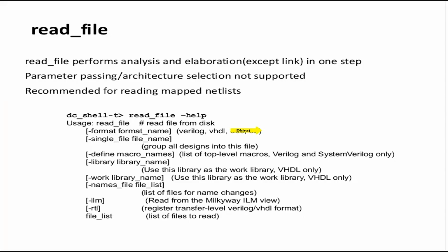However, you can use this to read the RTL also, if your RTL is simple enough. If your design does not have a parameterized design, you can go and read about parameterized designs in Verilog. If your design does not have a parameterized design, then you could actually use read_file for reading RTL also. Or let's say you are just compiling one module, just synthesizing and testing only one module. So you could use read_file. There's no need to do a separate analyze and elaborate.